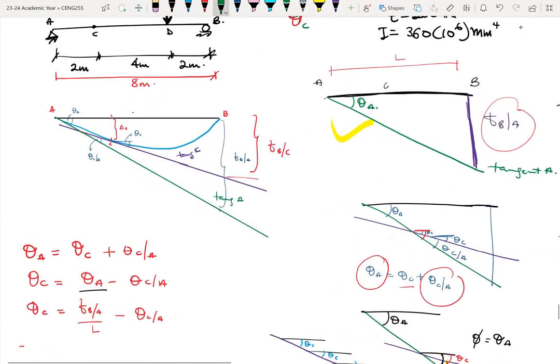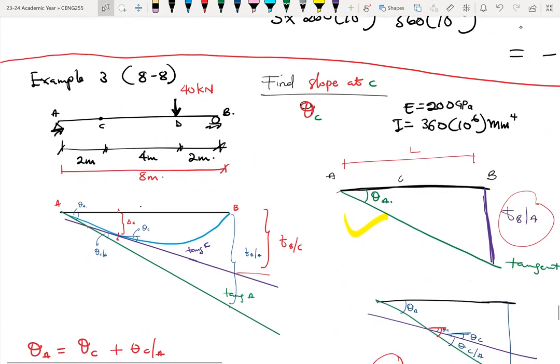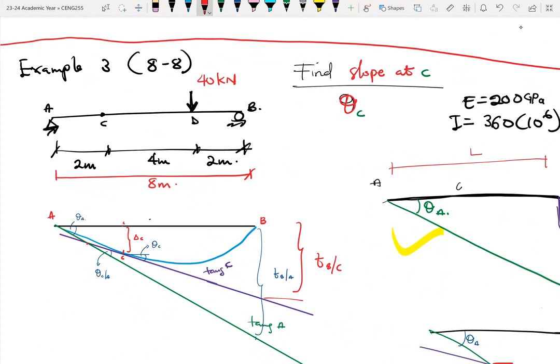All right. So drawing the elastic curve is just pretty much drawing the deflected shape. Okay. If you have a beam with a point load applied somewhere along the span of the beam, definitely the beam is going to deflect downwards. At least in this case, where you have only one point load, the beam will deflect downwards. So you always have this deflected shape. All right. Okay. It's important.